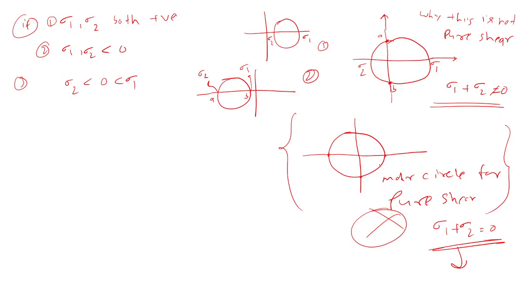Because you know twisting of a shaft is the pure shear condition, so from there you got this condition. Let's suppose you don't know that condition, then how did it come about? In pure shear, change in dimension is not happening, right? If you apply shear stress to this block, what will happen? It will change its shape, not dimension.